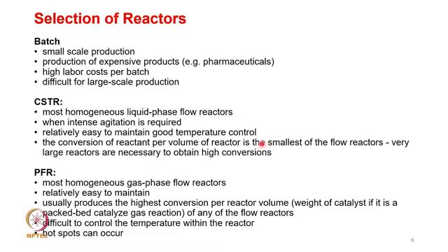But the key difficulty, or rather the key thing that we need to note here, is that the conversion of reactant per volume of reactor is the smallest of the flow reactors. So, as a result, very large reactors are necessary if you need to obtain high conversions.